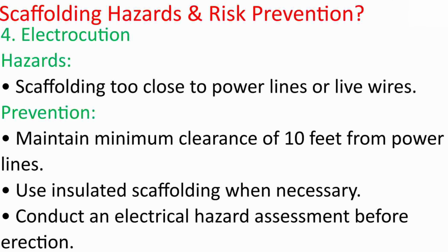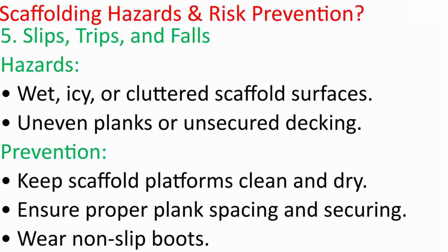4. Electrocution. Hazards: scaffolding too close to power lines or live wires. Prevention: maintain minimum clearance of 10 feet from power lines. Use insulated scaffolding when necessary. Conduct an electrical hazard assessment before erection.